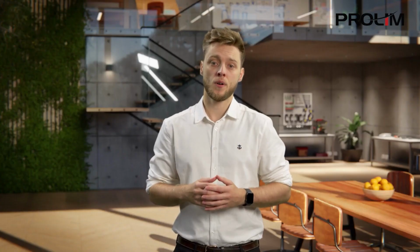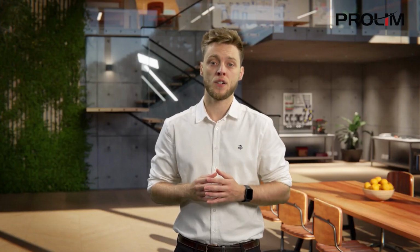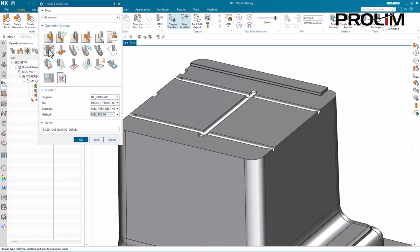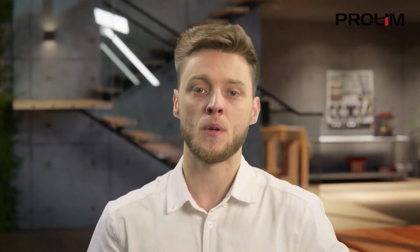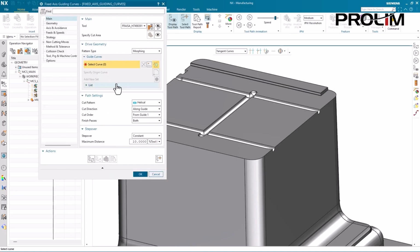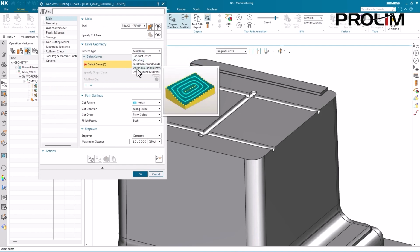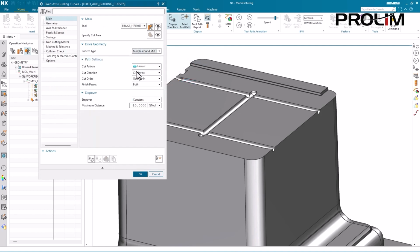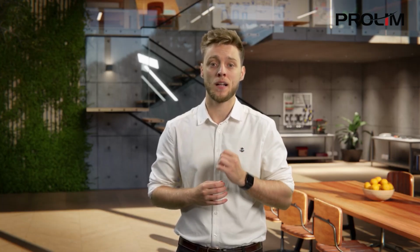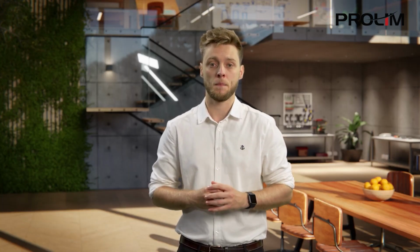To complete the machining process, we'll now create a finishing operation to achieve the desired mold accuracy and surface quality. We're using fixed axis guiding curves, an advanced finish milling operation that can follow the natural shape of the machined part, including undercuts. Setting the pattern type is an important step. For this mold core, we'll use the new morph cutting pattern, allowing us to machine a high quality mold and eliminate any manual bench work, shortening the lead time.